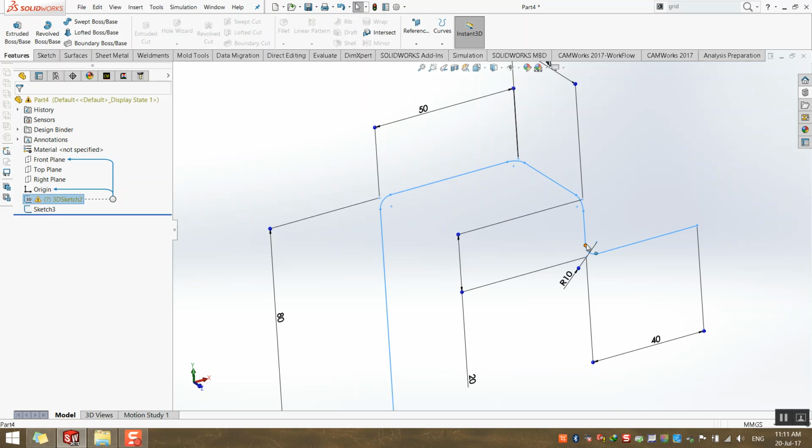You should make it as a curve. You draw it as a curve. No, but usually elbow with elbow. Elbow, you should draw it not with fillets. We will draw it with a curve, with an arc, because fillets have another concept, another parametric thinking. It's the same shape, but another parametric thinking. When you decide to do it in fillet and when you decide to draw it item by item.